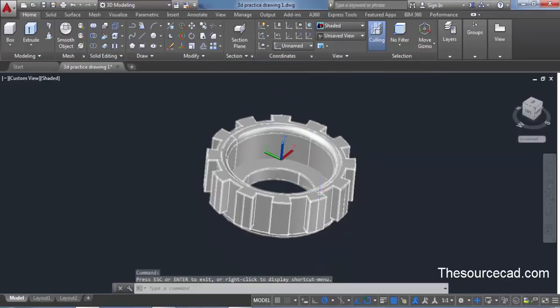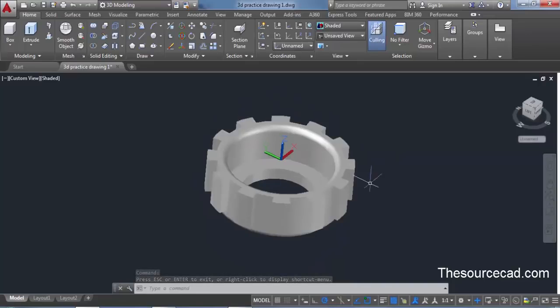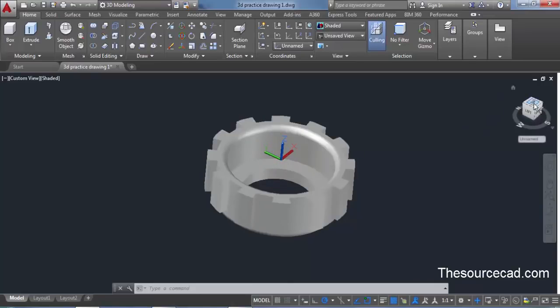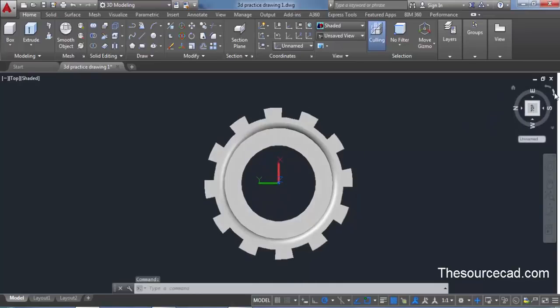Once you have the geometry, set your coordinates. Now currently you can see here that the coordinate is x, y, z, and when you click on the top of this view cube, you'll be able to see that the xy plane lies on the top of this geometry. So using FLATSHOT you can create 2D geometries, but only on the xy plane. So make sure that you select your xy plane before starting to convert it. So I've selected this xy plane as this.